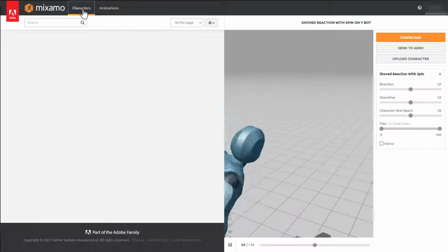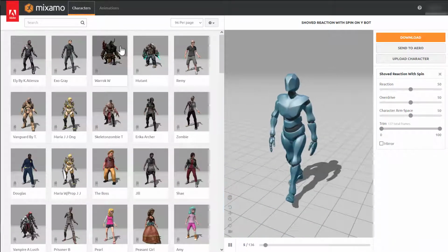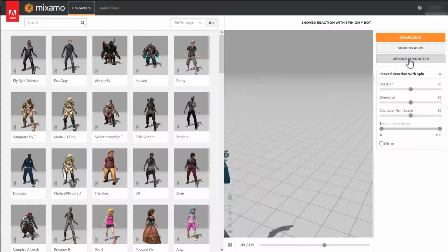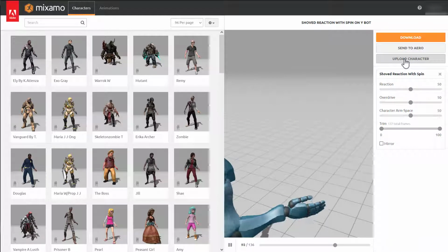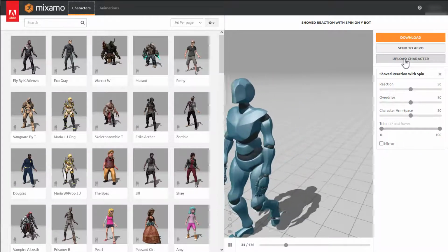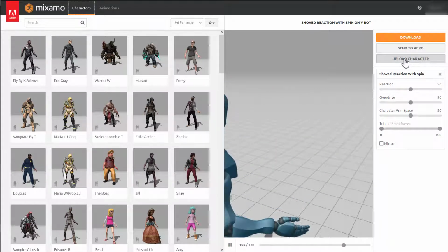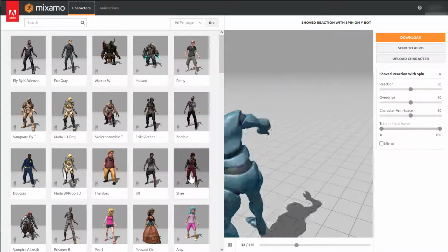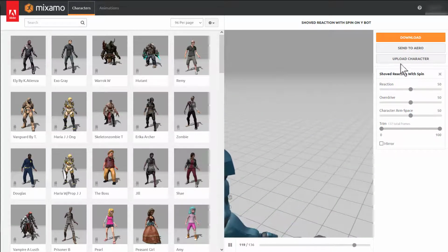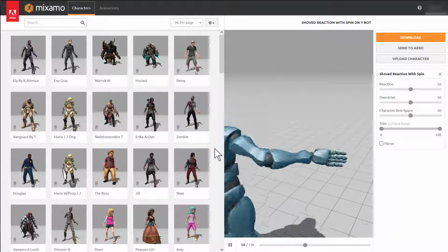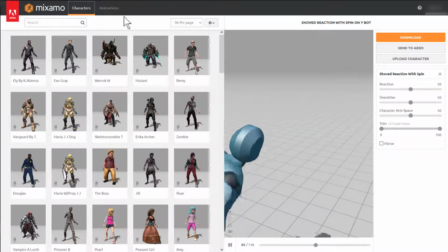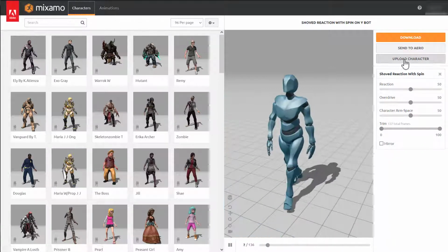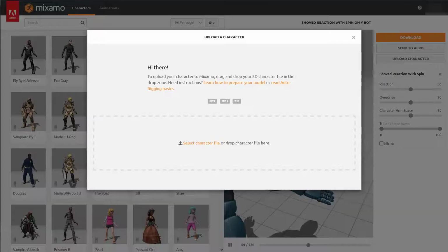If you want to bring in your own model that you have rigged, it can be tricky. If you have got a model that isn't rigged whatsoever, it should work. What you'll need to be careful of is that if you do have a rig, it needs to be relatively humanoid. So it's looking for arms and legs, and it wants either a T pose or an A pose, so it can reverse engineer that to be able to integrate with their existing animations and the rig that they use in Mixamo. So where I'll start is I'll just upload something I downloaded off CG Trader that isn't rigged.